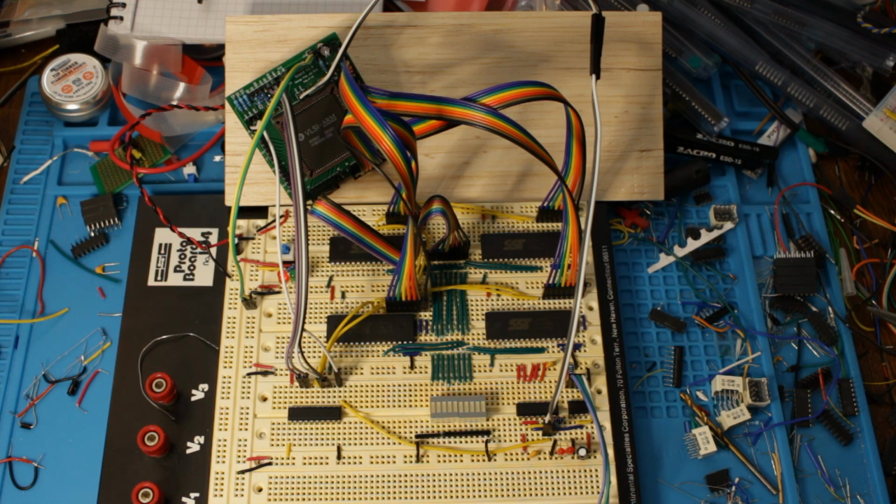You can see the 4 data bus ribbon cables there, one going to each ROM chip. There's this sort of grey and white cable that I've put an extension on, goes to the clocks. Yellow and green for power, because I couldn't find any red and black. Address latch enable, the white wire there, is connected through to the Phi1 on the breadboard.